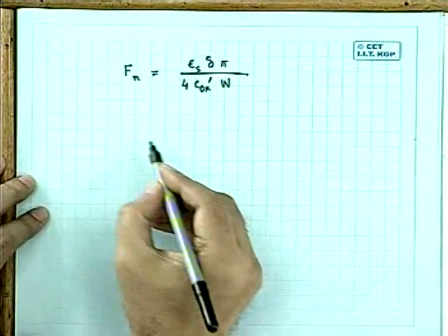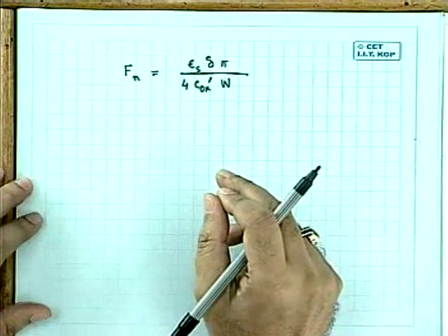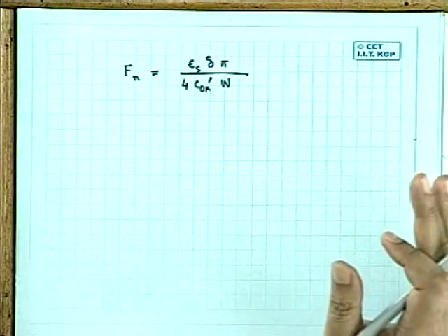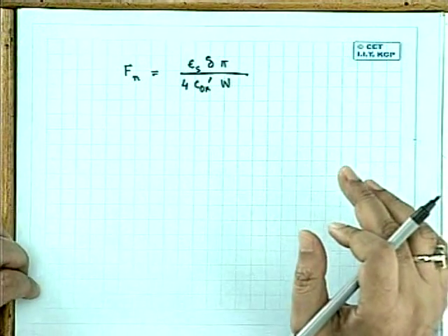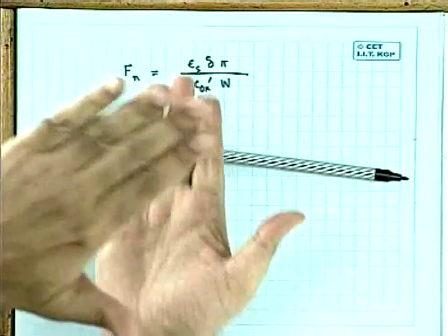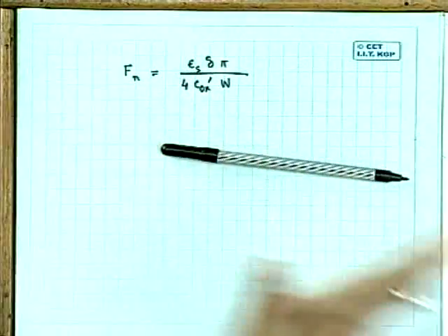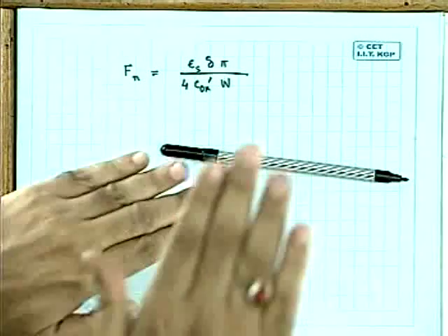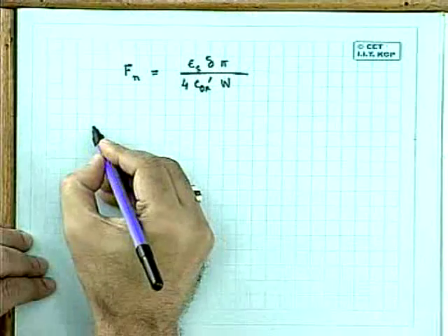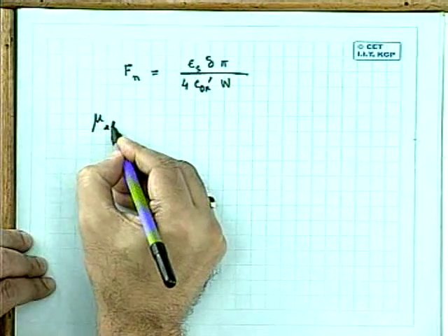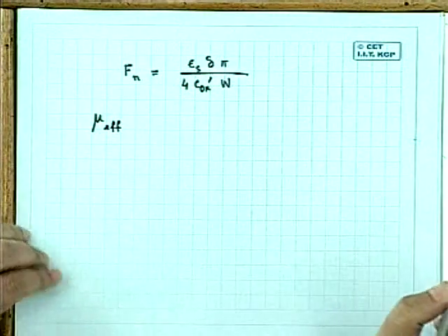Now, the mu s, which I have called the surface scattering mobility, surface mobility, does not consider the lateral field effect, the velocity saturation effect. Only the vertical field is considered. So that is further modified, and I now call mobility mu effective rather than mu.